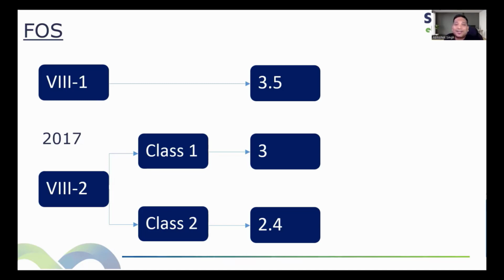Considering there is no fatigue and no rules are missing, for Class 2 also you can have design by rule. Class 2 does not mean Part 5. Class 2 only means that the allowable is different. You have to follow a different table for allowable. Factor of safety is 2.4. That is what Class 2 means. So by factor of safety, you can see the difference.